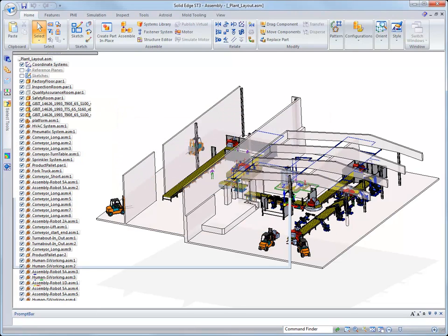A handy preview shows us the general look of the drawing, so choosing the right one isn't just by the file name. As I'm speaking, Solid Edge is computing all of the visible and hidden edges of the drawing views. We'll be placing 5 views: a top, 3 section views, and a detail view.